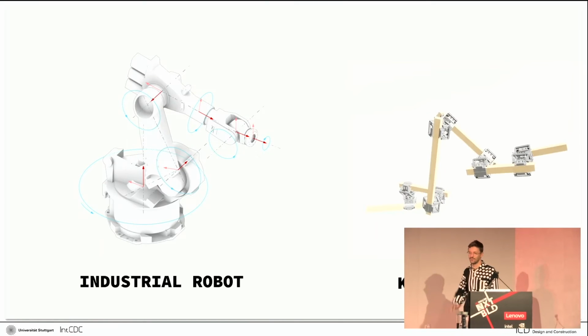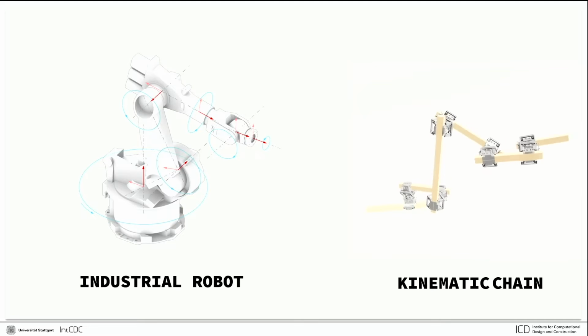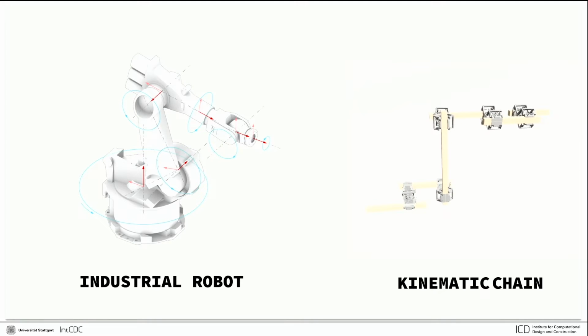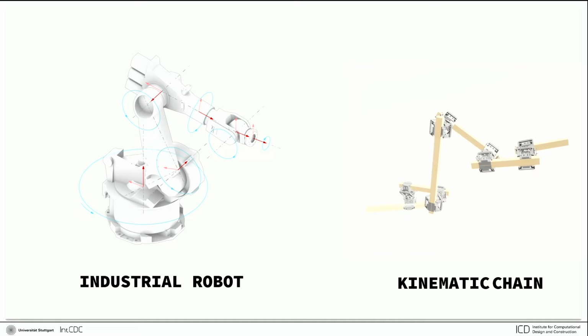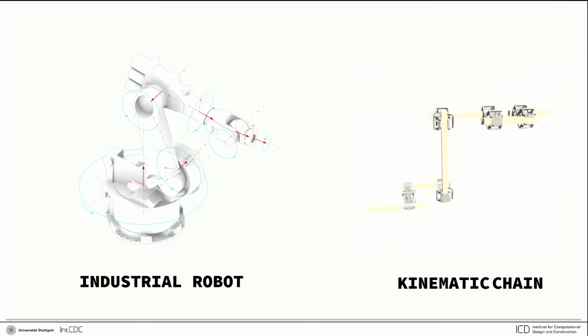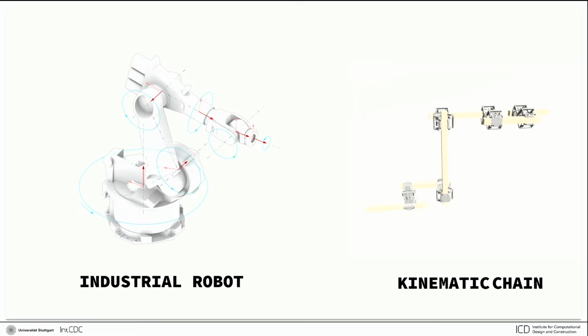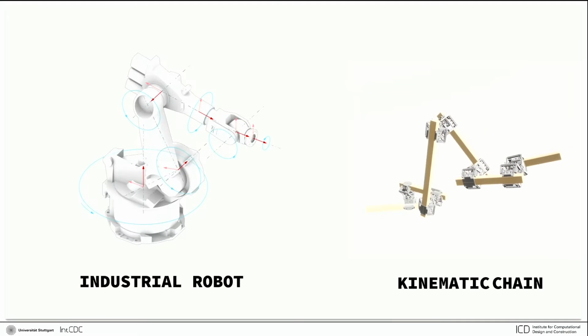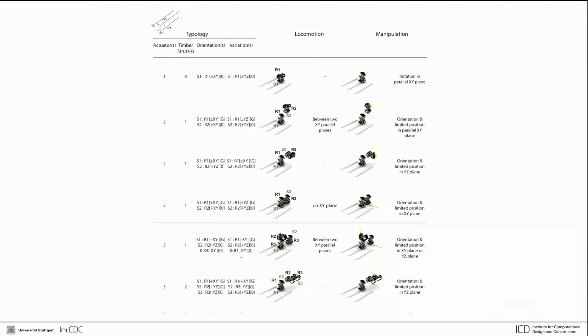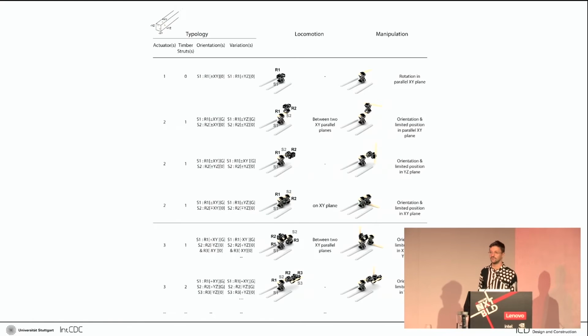This, however, poses a major challenge for the hardware, as the robotic actuator needs to be able to occupy any position in the kinematic chain. This is demonstrated when we look at an industrial robotic arm, as the first axis is generally quite large. And although we can possibly conceptualize our robotic actuator with such a large motor, it might prevent the whole system from being fairly lightweight and highly mobile, which are important for its ability to climb on and within the structure that it constructs.